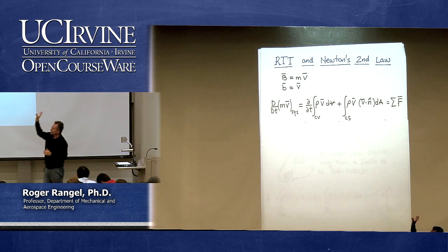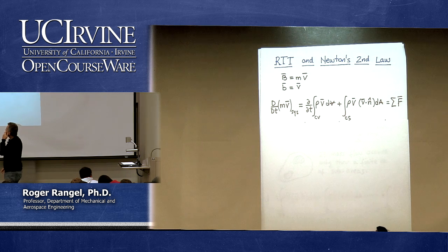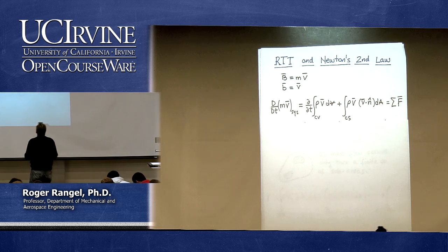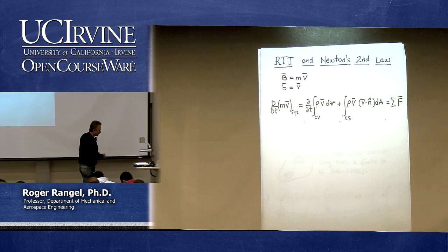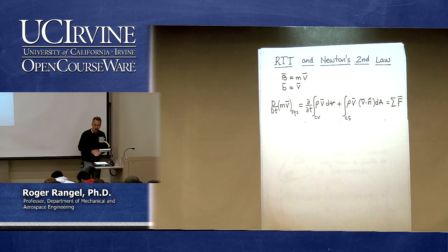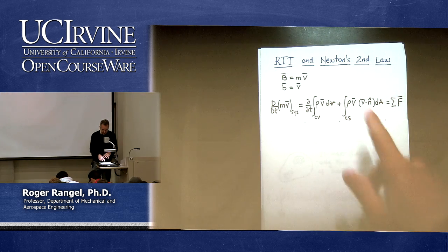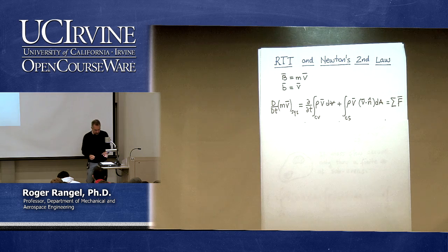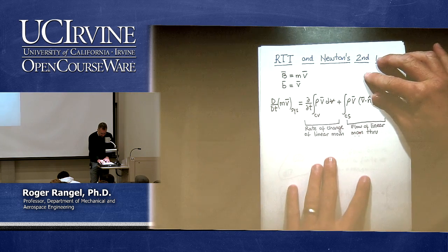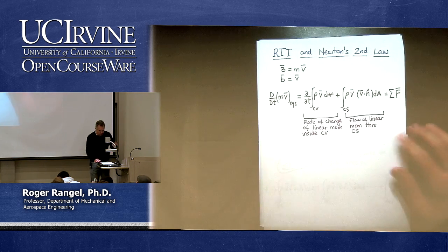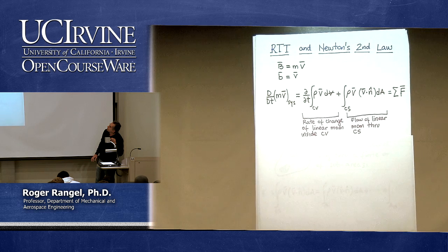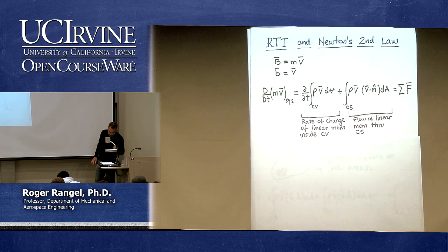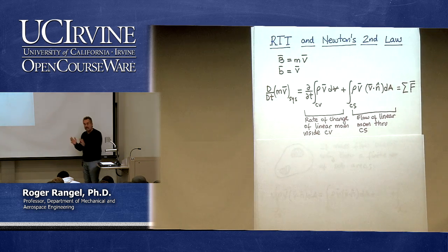And of course, what's in the middle is what comes from the Reynolds transport theorem, which is the two integrals, right? The integral over the control volume, which is differentiated in time, and then the integral over the control surface. By now, you probably know this, but if not, let's make sure you do. The meaning of those terms. The first integral is a time rate of change.